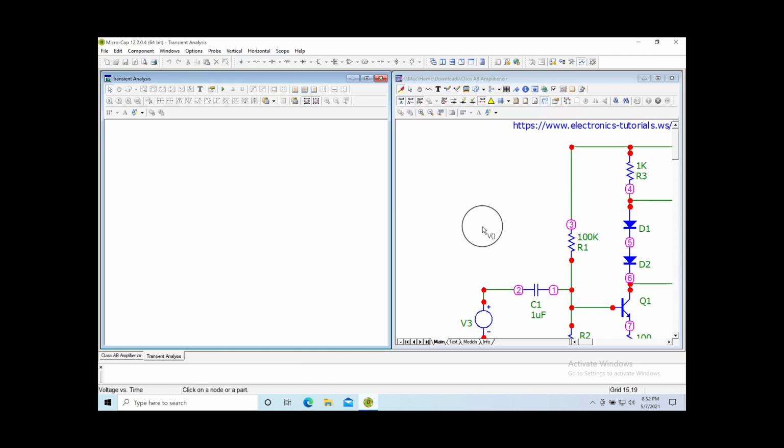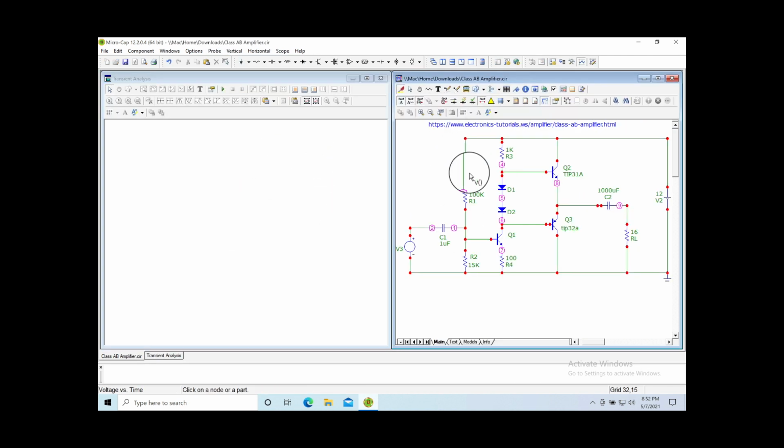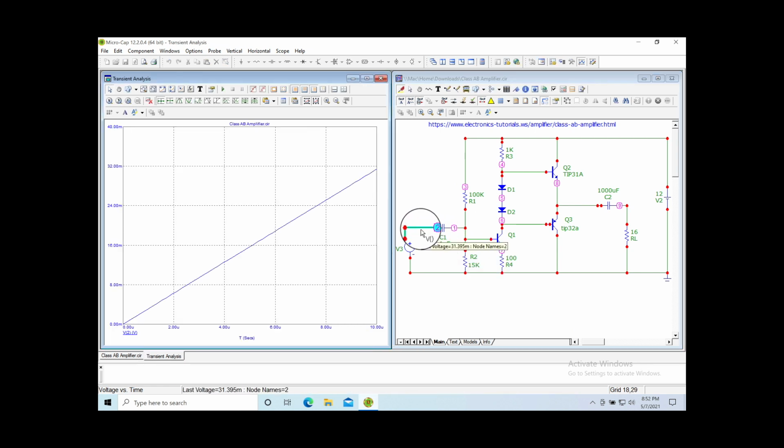Probe transient. Oh, let's resize that window. All right, there's our input. Whoa, okay, first of all, that's a problem. I look down here, scale goes to 10 microseconds, and this guy goes right off the screen. So my guess is that this generator is slower than the one before. The other one was 1 megahertz, if you notice that. It's pretty fast.